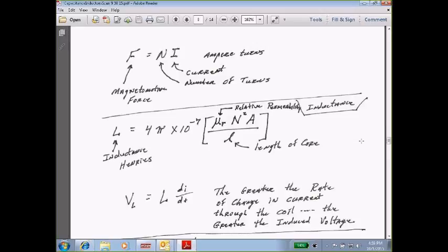So what's happening is we're applying 12 volts to the inductor, but then when we remove that voltage, the path for our current flow is through the spark plug, which has that gap, and if there's enough voltage potential, it will arc through that gap, creating a spark, and that's exactly what happens. In order to do that, we have to have an induced voltage that's many, many times greater than that which caused it, and that's inherent to an inductor. Well, what controls how much that induced voltage is going to be? Number of turns and the current.